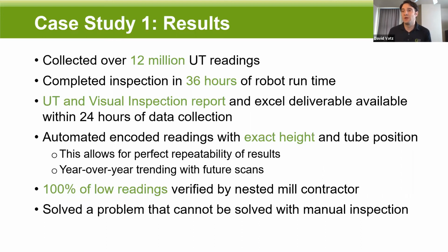So we can scan on composite tubes, on overlaid tubes in recovery boilers. The most important thing is just understanding what the metallurgy of the composite or of the overlay is. So the short answer is yes. Long answer is we would want to make sure we understand what it is so that we can calibrate the sensors correctly.